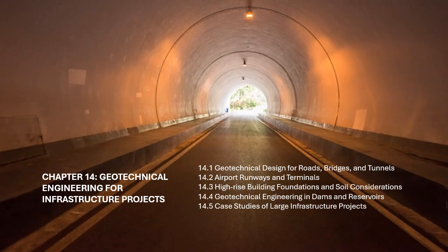TBM and excavation method selection. For tunnels, selecting the right excavation method, such as tunnel boring machines, TBMs, or cut and cover techniques, is crucial. Geotechnical engineers assess soil and rock conditions to determine the most efficient and safe method of excavation, ensuring minimal disturbance to surrounding areas.